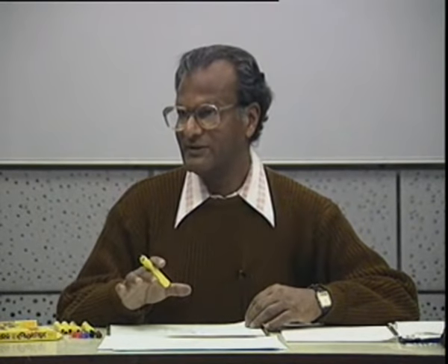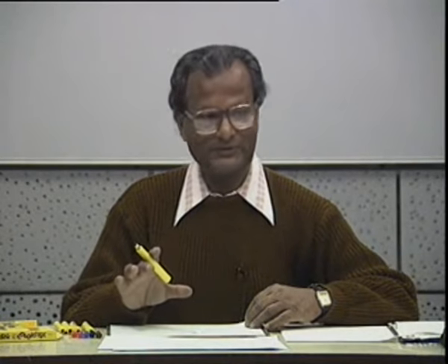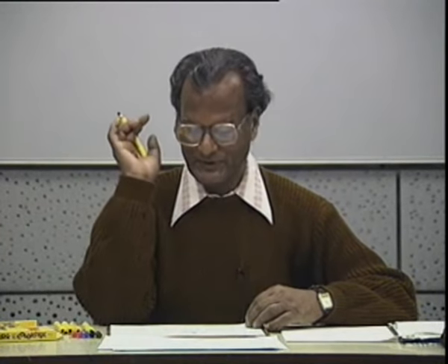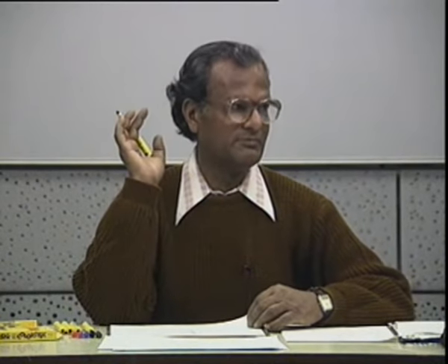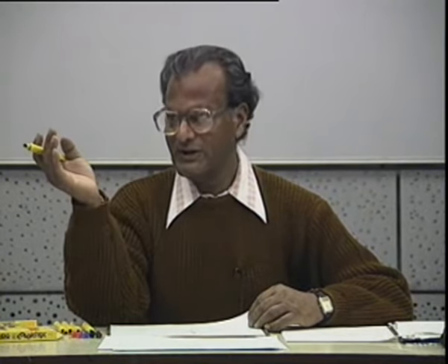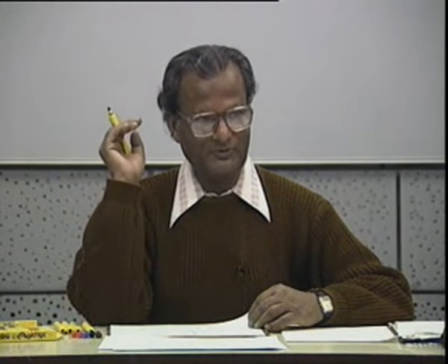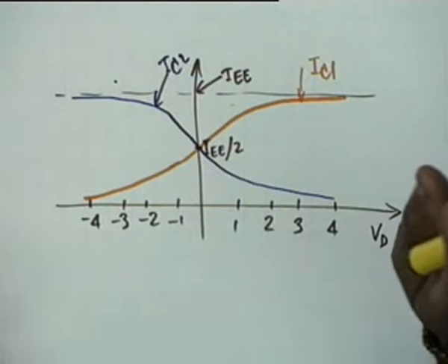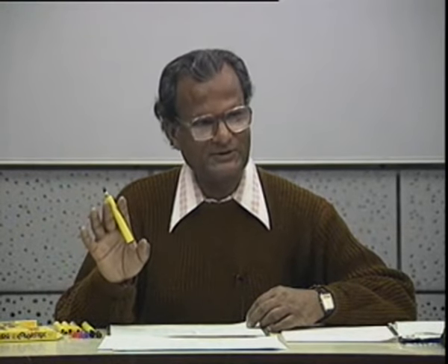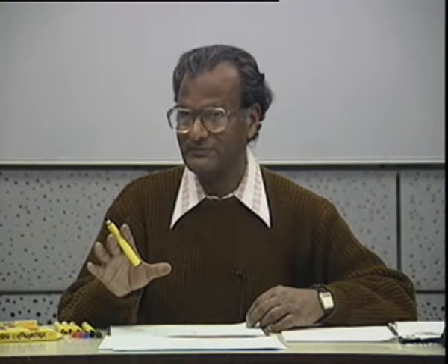Our purpose is, however, analog, and therefore we want to see if we can get a linear relationship between the output voltage and the input voltage. This is obviously a nonlinear relationship. We don't want any transistor to be cut off. We don't want any transistor to be in saturation. So we must avoid them. Let us see how to avoid them.